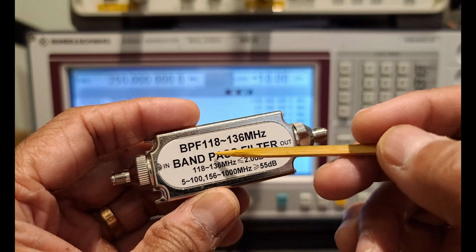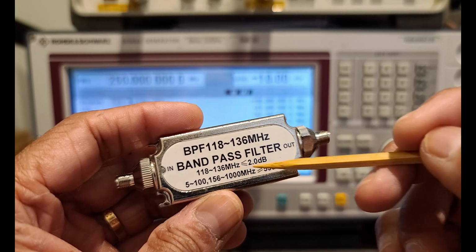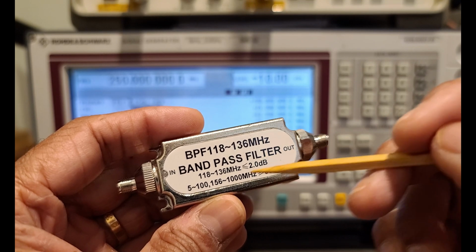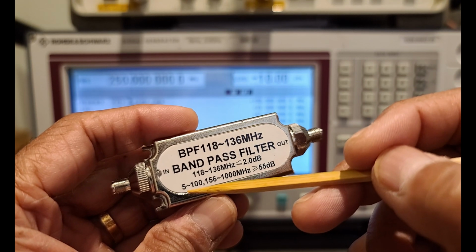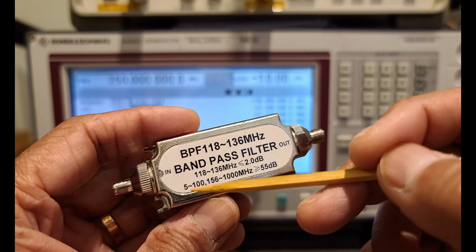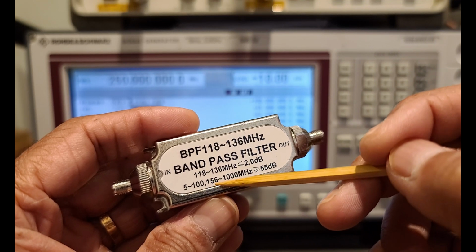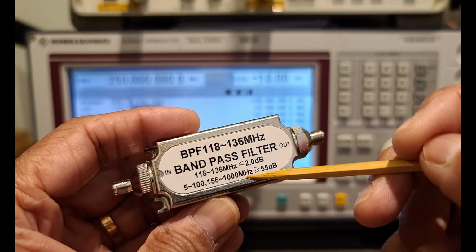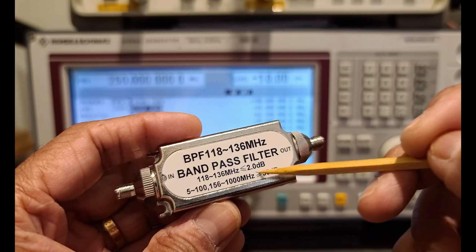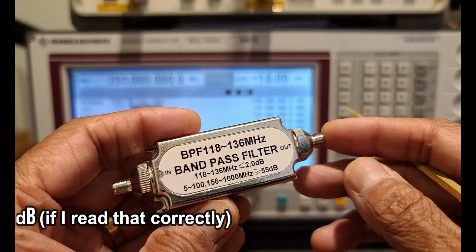Between the spec range, 118 to 136 megahertz, it says it's about 2 dB loss. And between 5 to 100 megahertz, and then 156 megahertz to 1 gigahertz, there's over 55 dB rejection.